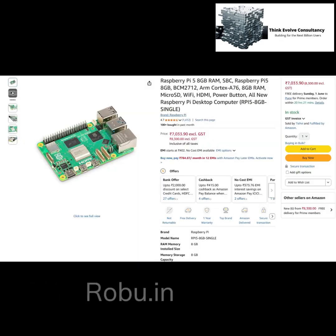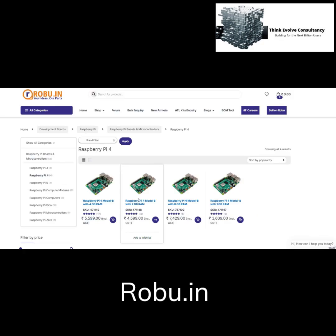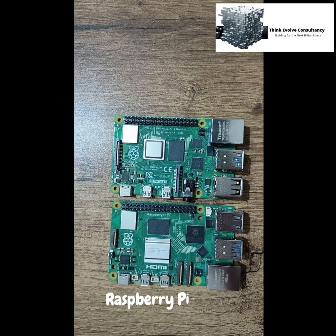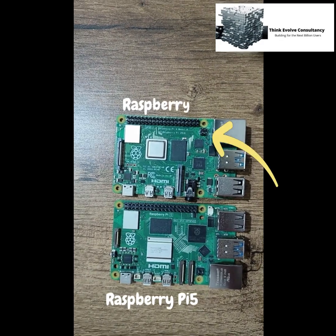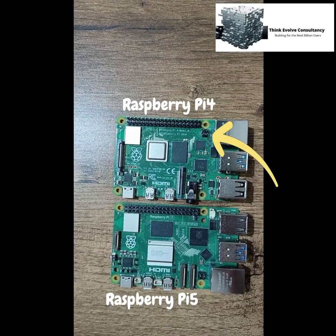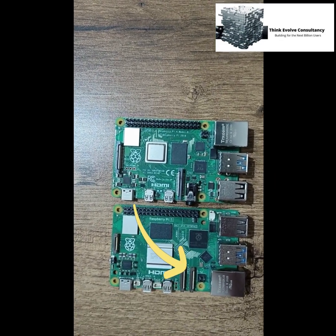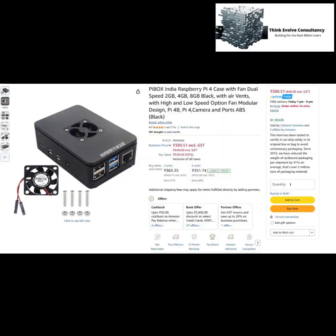I bought this beauty from Amazon. But it can also be bought from Robo.in, which is a very successful Pune based company. The form factor for a Pi 5 and Pi 4 are similar, except for the alignments of some components. So be careful while buying the cases. Not all cases are the same. This case says it's for a Pi 4, and don't make my mistake of believing that it will fit a Pi 5.